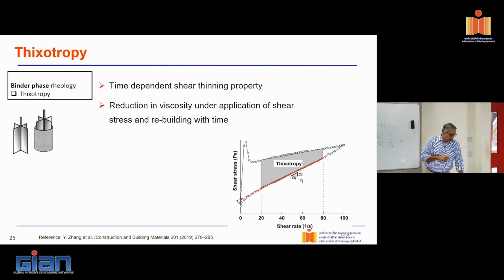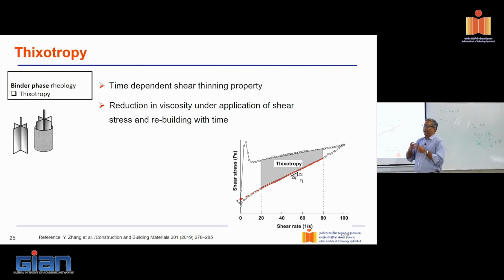And let me see what other gyan I wanted to give. Yeah, so thixotropy basically also entails the energy that it would take for me to smash the structure inside the cement paste. Okay, now the converse of it can also be looked at. Suppose I have a cement structure. Where is that going to come in handy? If the material has some skeleton inside, it's able to give me some resistance because of the skeleton. Where is that handy? Well, I can count on it to keep its shape, right? It's behaving like an elastic material. As simple as that, isn't it?